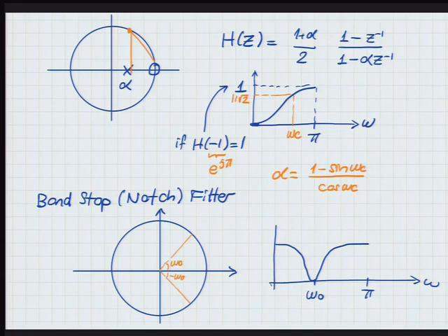Remember, it's kosher to put zeros on the unit circle. You mean on the unit circle at those frequencies. So you're saying put one here? Okay. And then another one here. So it's a complex conjugate pair. So the product of the two terms, giving us these poles, will give us a real coefficient polynomial of second degree,